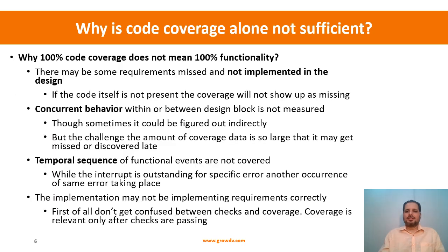See, the implicitly generated coverage metrics are very attractive because we don't have to do anything, and the simulator will generate it, based on the code that I have written, right? So I have written a design which I am trying to verify, and the simulator is telling me how much of that particular code has been covered: which lines have been executed, which conditions have been met, which branches have been taken, which state machines have been exercised. It's telling me everything.